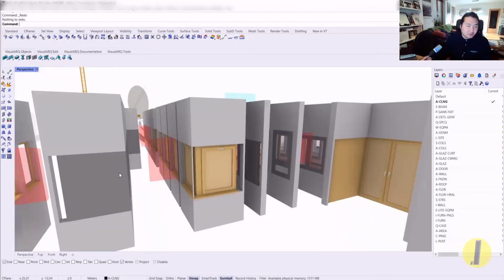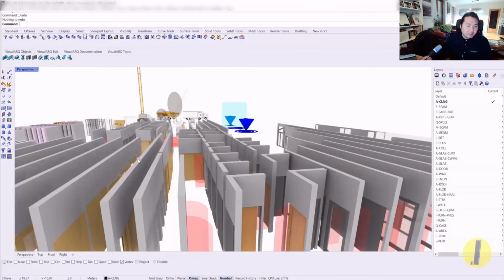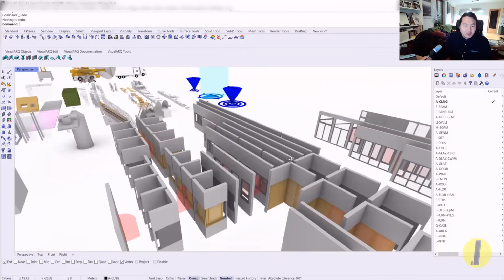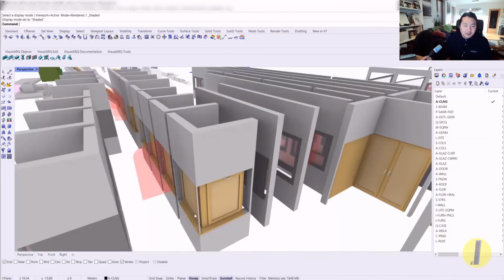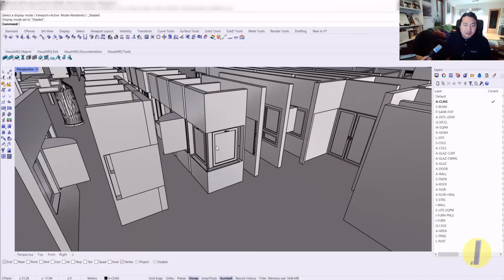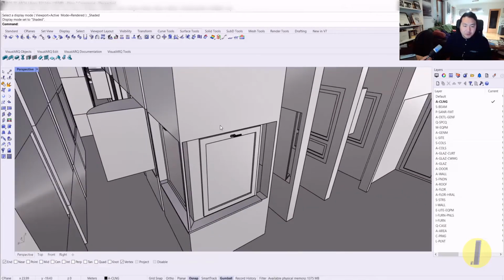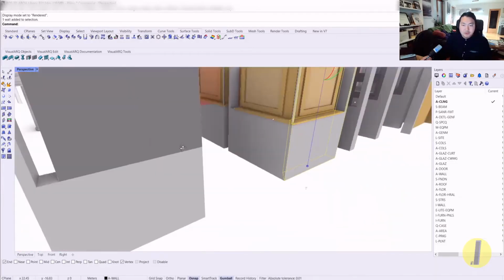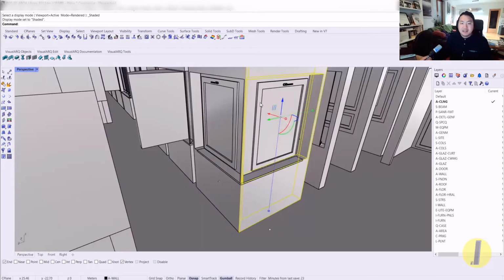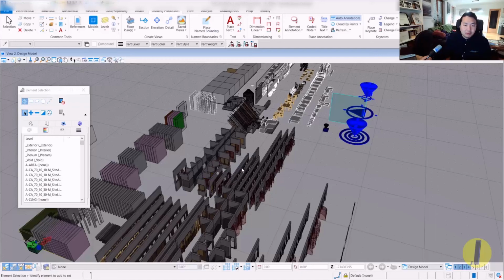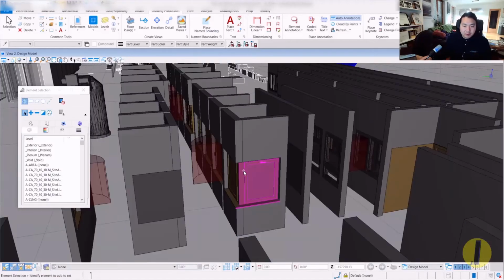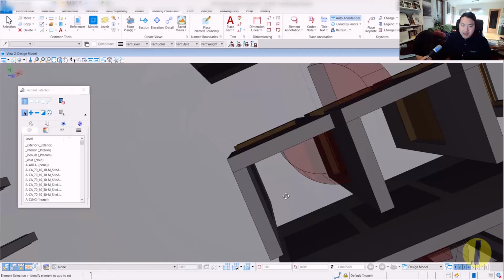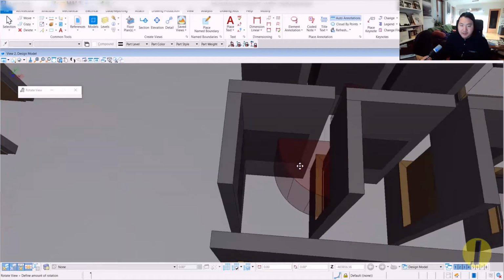Why each software displays differently, with this, the window panels appear, which happens to some of the doors or windows dealing with coarse fill view. And also, if you look at this corner window here in visualARQ, unfortunately the wall geometry is not accurate. So this sort of issue always has to be discussed between the architects. When you go to openBuilding Designer, let's have a look. Yeah, the wall geometry is quite good and precise, but just these coarse fill panels are appearing.